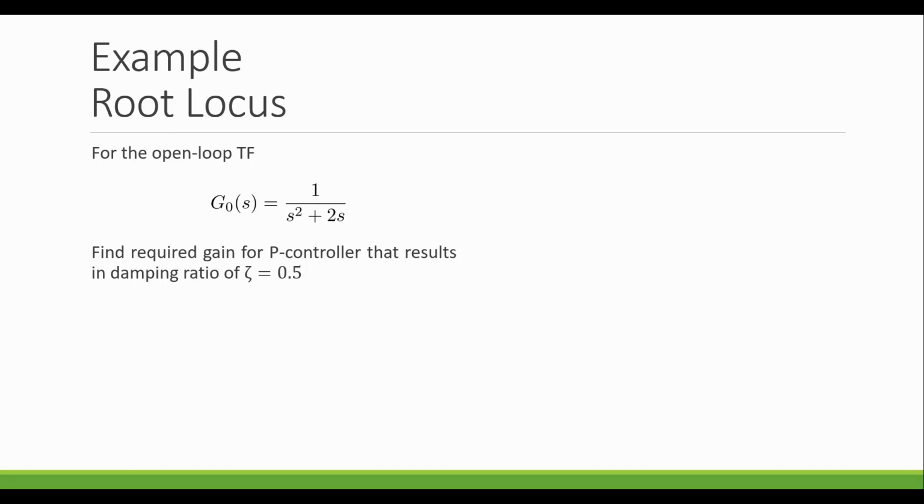Now, I'm selecting the P controller a little bit arbitrarily. We know it will work for this system because we just saw in the previous part of this example that it did. And I'm arbitrarily selecting right now a damping ratio of 0.5. But where might the performance metrics come from? Where might our selection of zeta and omega n come from?